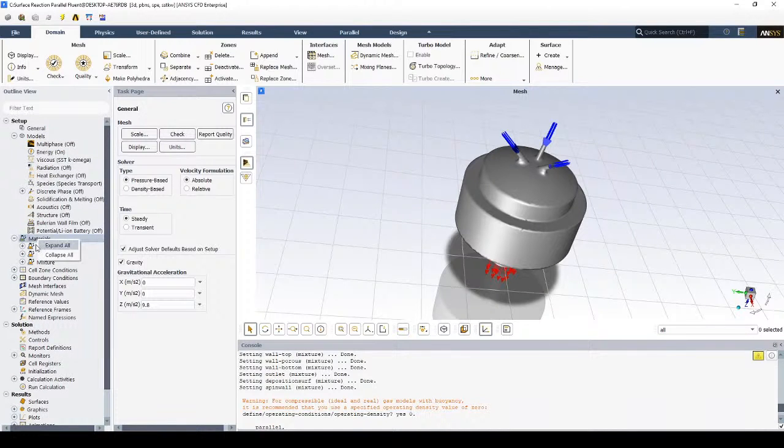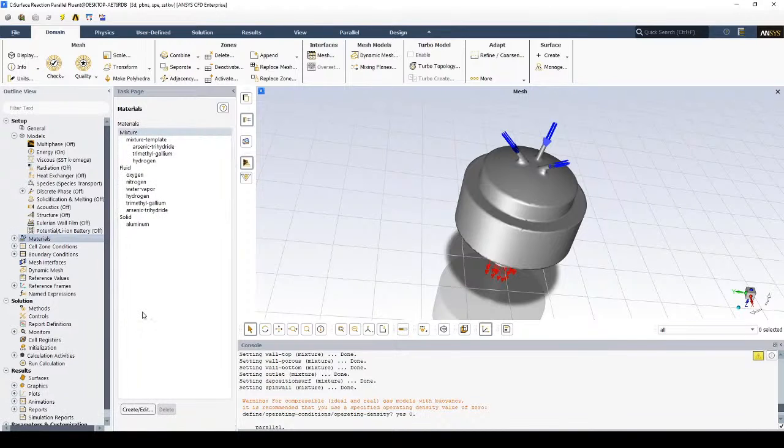So the first thing we want to do is bring in some more materials. Right now I have 3 mixtures, 3 species in one mixture all sprayed in here. These are our reactants. We also have a product, so some of these will generate products, and product will be a mixture of the actual deposition and also other gases and such. And we also need some site species. So basically, we need to add in a few more materials.